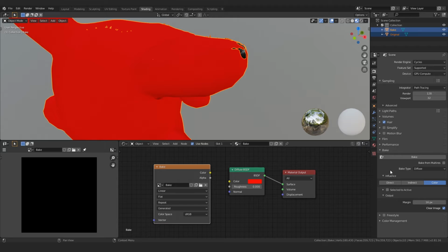And that's a black and white map that's usually overlaid over the top of the colored albedo map to give the illusion that there is shading on top of that color. And this is a great way to create a smaller sized color map that can be mapped across the surface of an object, and then using that ambient occlusion map can allow you to change the color variation of your model. So that's some technical 3D texture and material design talk there, but essentially what we want here is we want diffuse and color only.